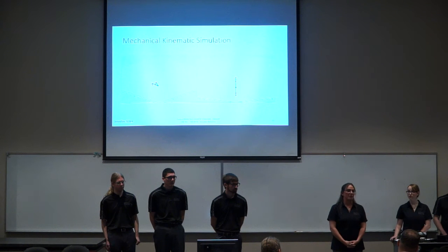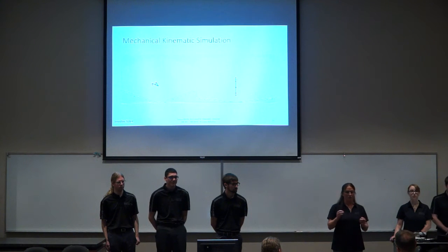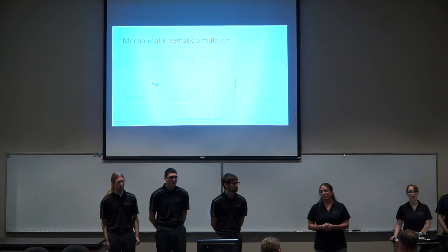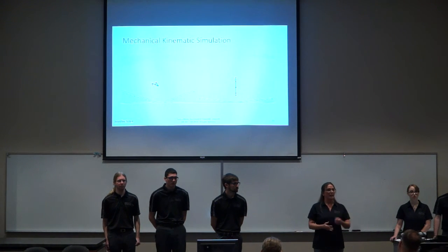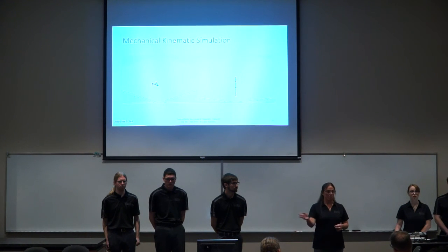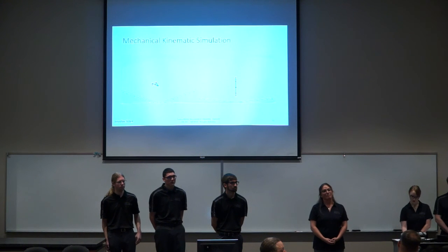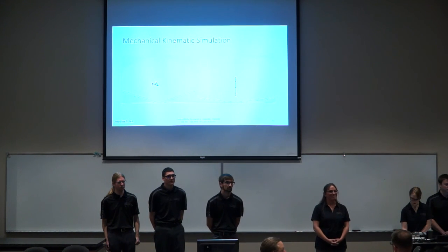This is, we know the lengths of, in robotics, we make a DH table, which gives the links of where each of the actuators are connected. And from there, taking that information, this is exactly the prototype that Dr. Gentilini has made. And modeling after that and knowing the limitations of how it can turn, the restrictions that the robot can make within the workspace, we're able to put that into Matlab code and derive the actual robot that you see. One thing you can also do in the future is you can also draw your mechanism on Matlab. Yes. And animate that using HD transform functions that are built in Matlab. Okay, great. 102, please.